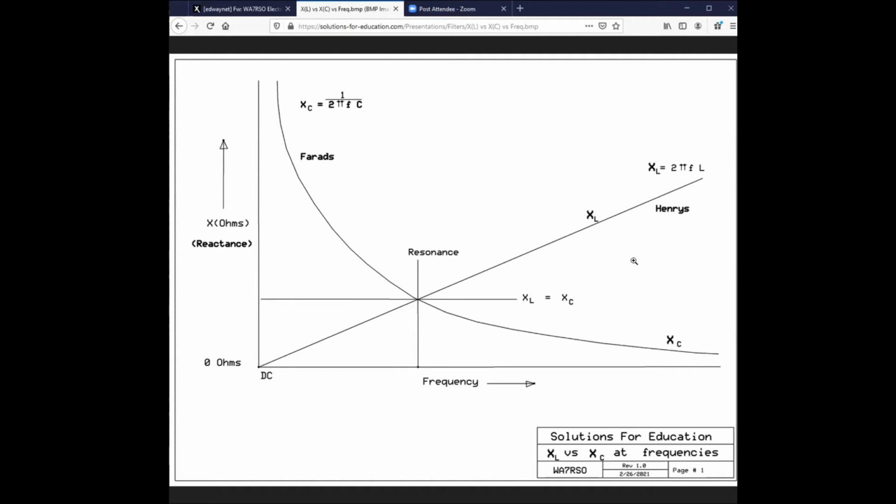well, just a second though, that's wrong, isn't it? Think about it. I said change. You see, if you change 1 amp per second, in other words, you go from 1 amp to 2 amps in a linear fashion, 1 Henry will develop 1 volt counter EMF during the entire second. It'll hold 1 volt at that change. If you change the time and make that a millisecond, it'll develop 1,000 volts instead of 1 volt. Now that's the definition of a Henry.